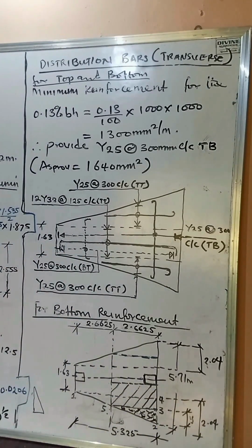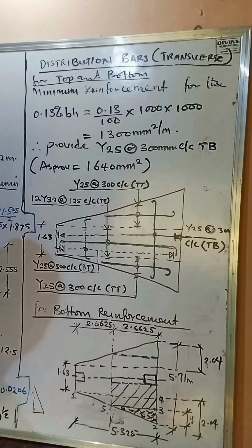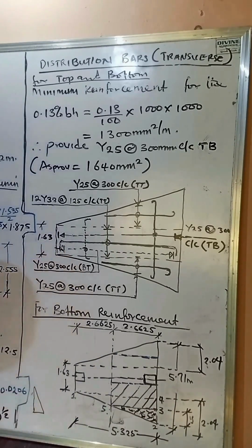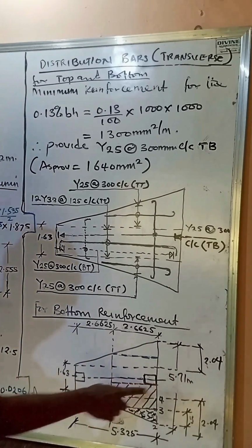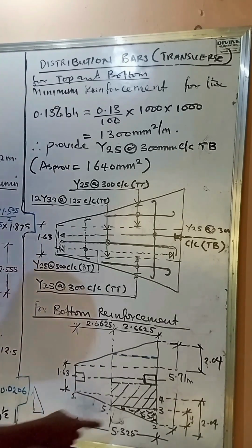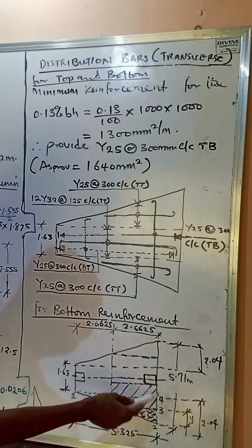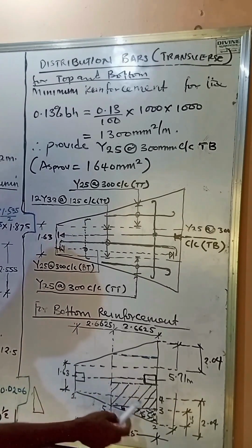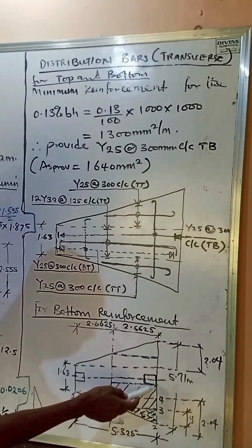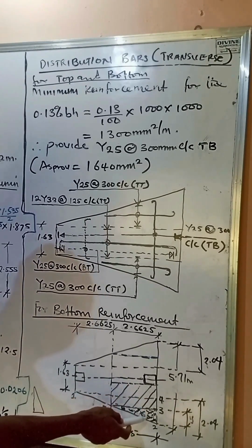All right. Now, for us to do that, we need to multiply the pressure times the area of this region shaded times the centroidal distance to the surface of the column. But in doing that, I'm going to discretize that portion into two parts. These other parts represent a triangle, these other parts represent a square. So the pressure will act on this part and will also act on this part. So we'll calculate the moment of that pressure about the surface of this place when it acts on this rectangle plus when it acts on this triangle. So the two portions.